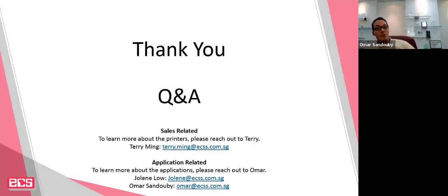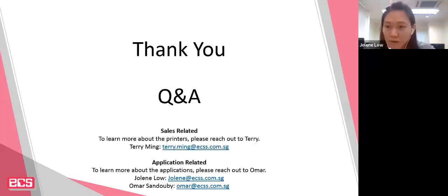The surface finish is smoother, and this is very important for investment casting, especially for jewelry, when you try to get a smooth surface finish. So again, the compound is different. The support wax and the build wax are quite different in a way. Yep, and in the last video, you see there's a sparse support wax creation. So support wax can be created as sparse support, and it can be easily removed, and the wax that you actually cast is fully solid, so you can get the actual part itself.